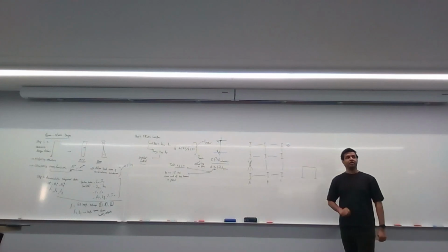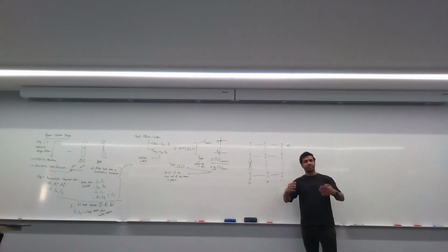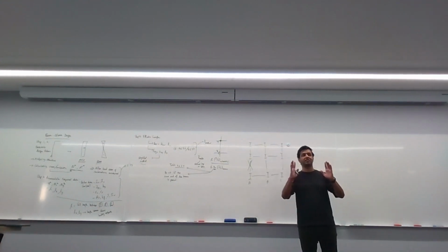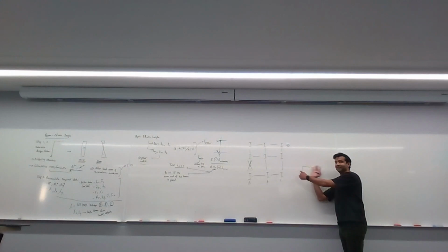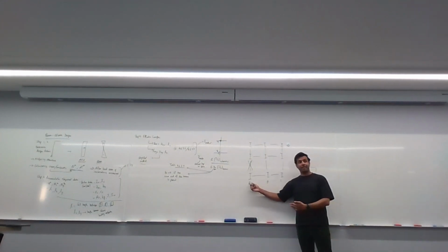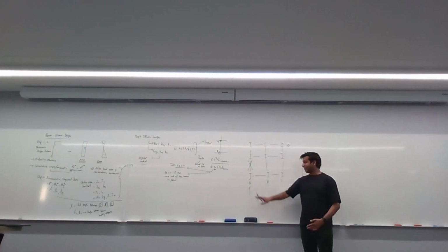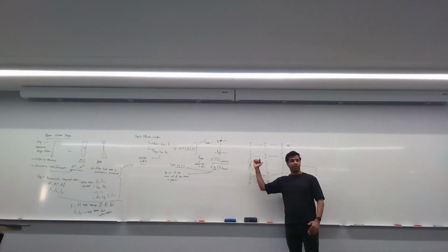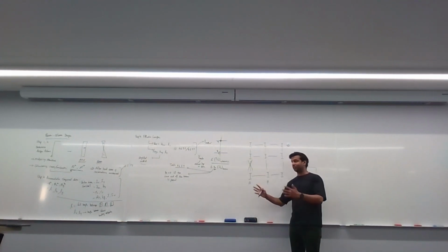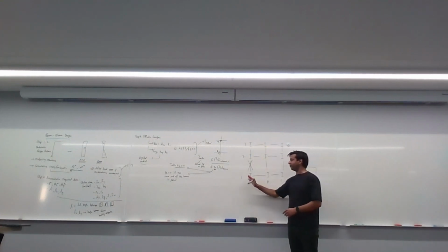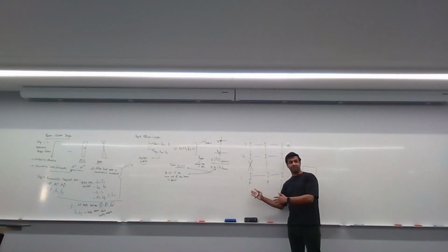So if the code is referring to a frame that is braced, they are asking, is the frame braced against loads acting this way? If you're worried about loads going the other way, then I shouldn't be talking about frame A. What should I be talking about? Frame 1, 2, and 3. So again, is frame A braced? Yes. Frame A is a braced frame.